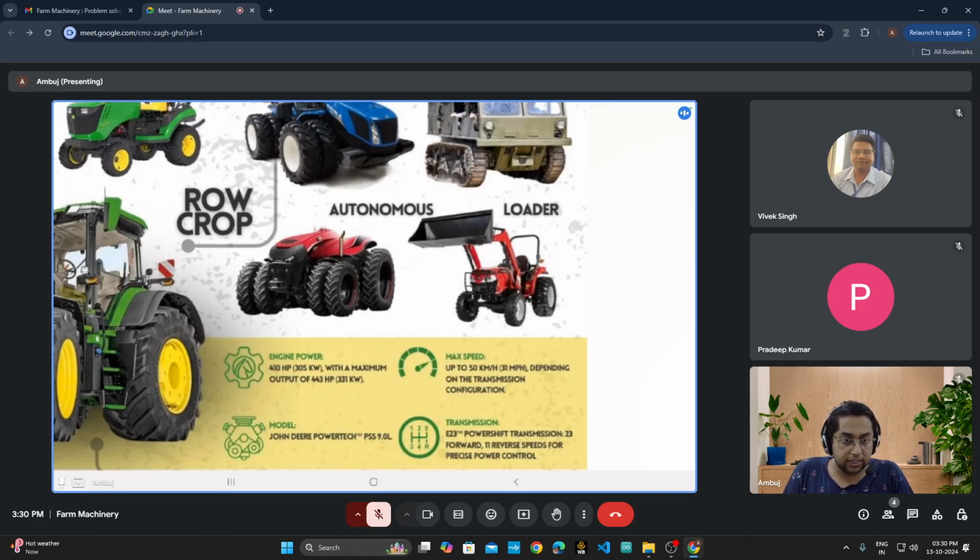Now comes the role of steering. Using the IMU sensor, you will have real-time correction angles that are fed to the microcontroller, and from the microcontroller, the steering angle correction has to be made through directly turning the steering. For that, we have provided a belt and pulley system. We have connected a pulley and a motor to the steering, so the steering would be autonomously turned by the DC motor or gear motor.